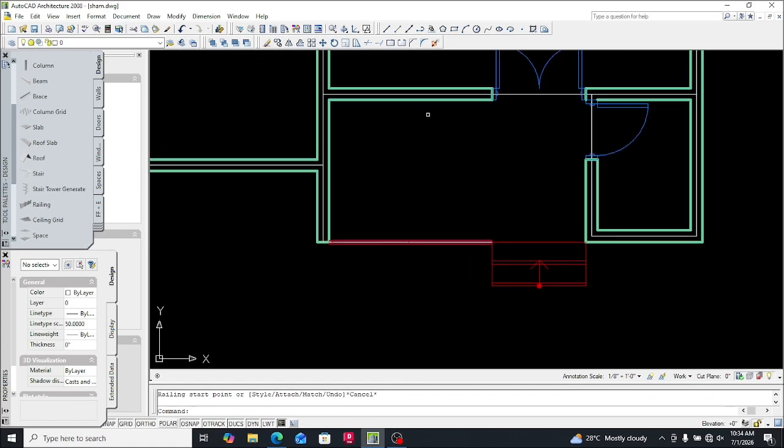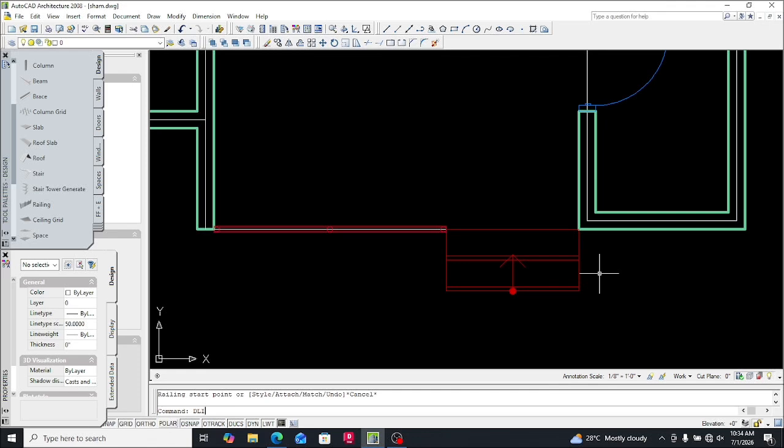And already at the porch, you have to get a step down, so the porch becomes 146. That is 1 foot for the hardcore filling, then plus the 6 inches, making 146. So the stairs, you have to get 2 rises, 6 inches. So the stairs should be 1 foot. Let's see if it's also 1 foot.